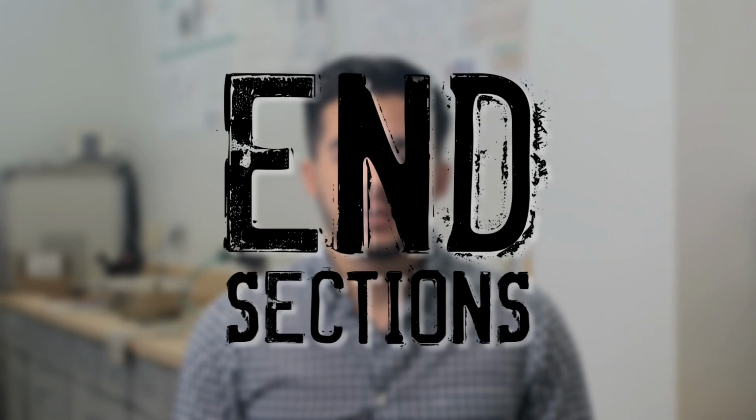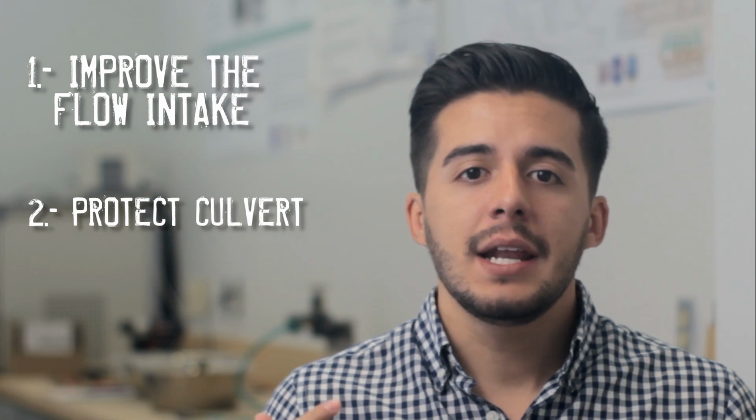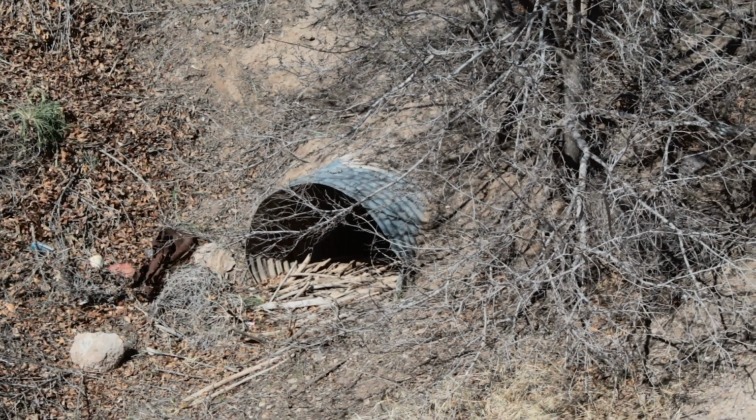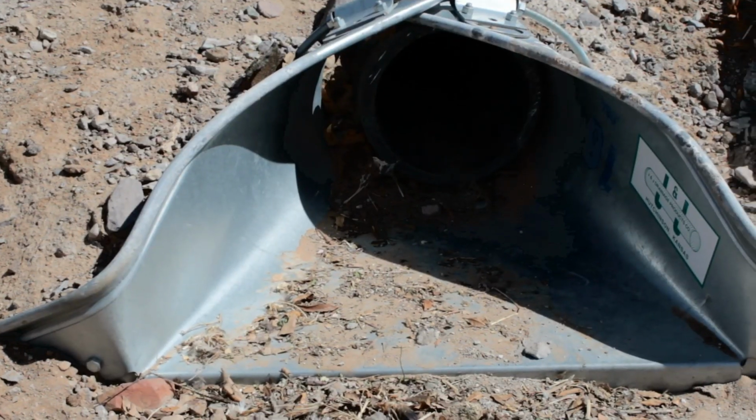Another important characteristic of culverts are the end sections. They are used to improve the flow intake, protect the culvert, and improve the safety of the traveling public. Examples like this are defined as no end section. A metal or concrete end section has a flared shape to improve the flow of water.